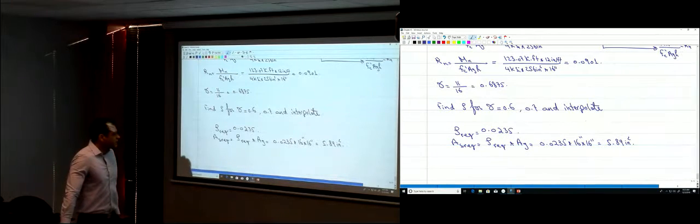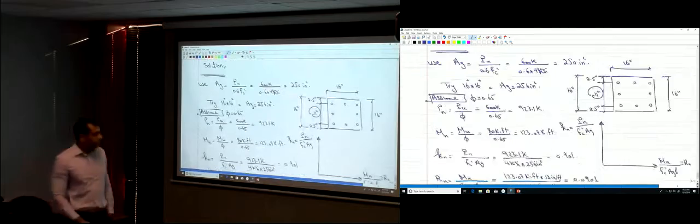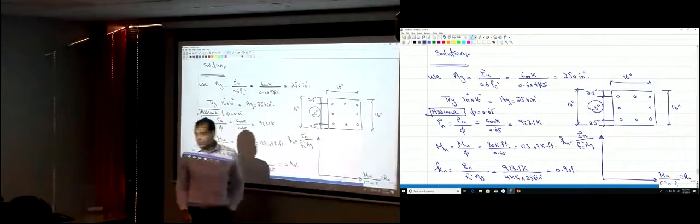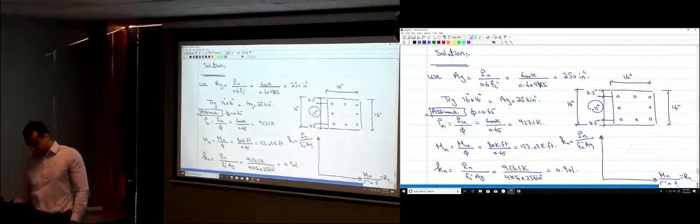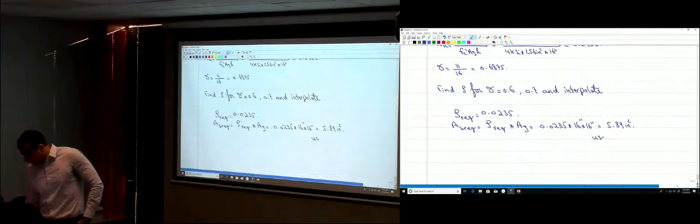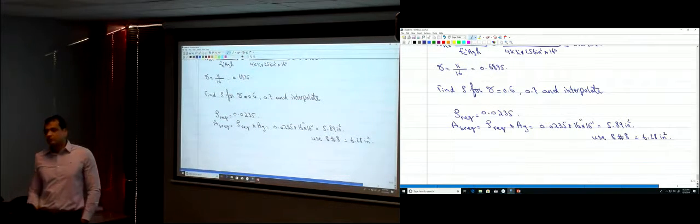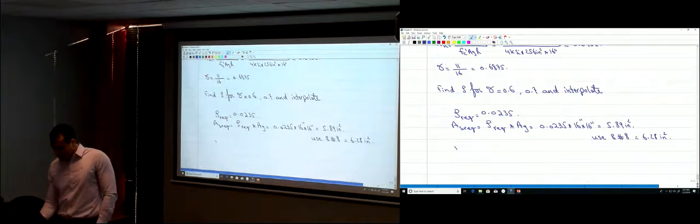You would say use number 8 bars, right? You have to have the steel distributed among the 4 faces over here. So you need 3, 6, you need 8. Okay? So 6 number 9. So instead of using 6 number 9, we're going to use 8 number 8 bars, which is equal to 6.28 inches squared. And then check the distance between the bars, design the stirrups, and so on.